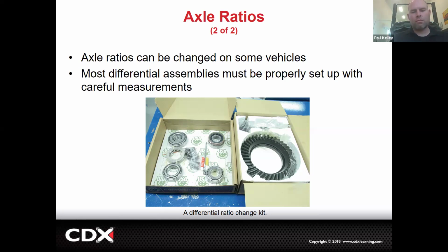other. You're going to end up replacing that ring gear, and that previous pinion that's worn to the old ring gear is going to imprint its wear onto the new ring gear. Now you basically put a new ring gear in there, and the old pinion ruined it. That's what I'm telling you. All right, cool. So if you're going to change it, you change it as a set.